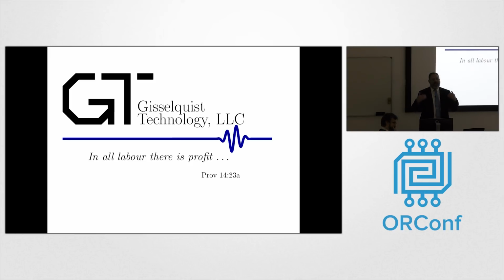One of the problems is as I've moved this core to hardware after hardware after hardware, I've kept having to trim it or expand it. And so it's got all kinds of features within it. You can use this feature or that feature, pick what fits, and I had to prove it for all the different features. SymbiYosys has the ability to say, I want to prove it where the parameters are this, this, and this. And so if your core is parameterized, you can prove all of the assertions given these parameters are true. Okay. Great work. Thank you very much. Thank you.